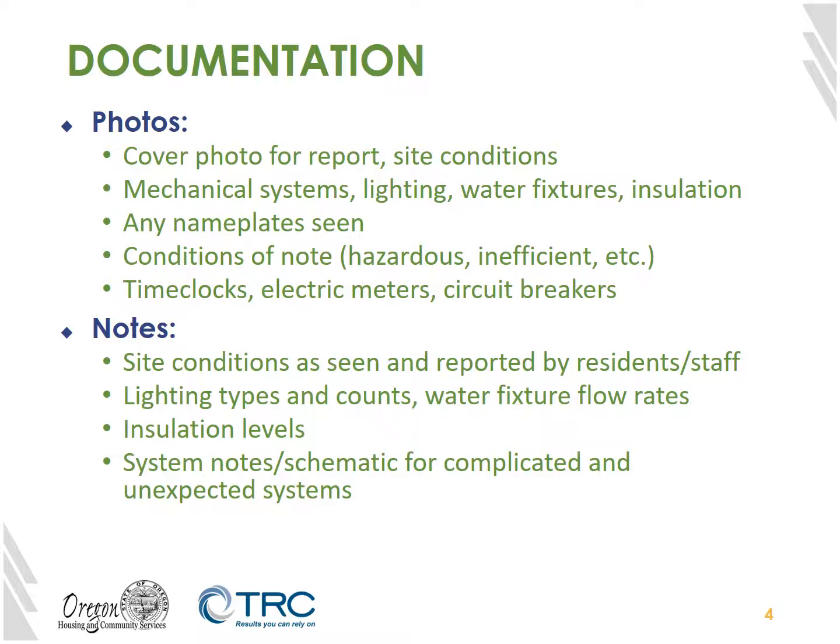Additionally, the auditor will need to take detailed notes on the property, including types and counts of lighting and water fixtures, insulation levels, and notes or schematics of any complicated or unexpected systems.